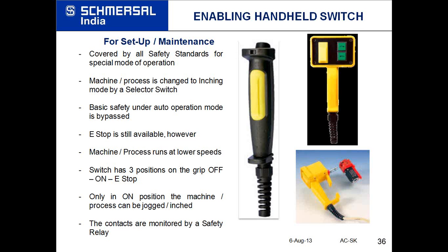So this means the emergency stop is still in service, and the emergency stop push button is in the hands of the operator who is doing the setup or the maintenance. So we have certain minimum maintenance safety available when we do the maintenance or setup. Also, under this condition we can run the machine at lower speeds if possible during setup and maintenance mode. There should be a key operated selector switch, which should